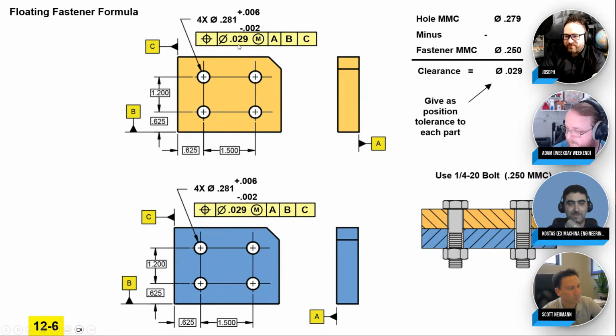I wasn't even thinking about stack ups at that point. That's a good point. You do get more after stack ups. If you just locate one hole, square versus round, it's like, oh, great, you get 56% more. But then when you go to the next hole where there's a stack up, oh my gosh, you get even more.